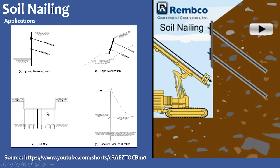Here you can see that we have inserted a slab and we are preventing its failure with nailing. Also, in the concrete gravity dam, we have uplift pressure at the bottom of the dam. This uplift pressure can create an upward force on the dam structure, which can make it unstable. So in that case we introduce nailing here so that this dam won't fail. This is another concrete dam stabilization application where we go for nailing.